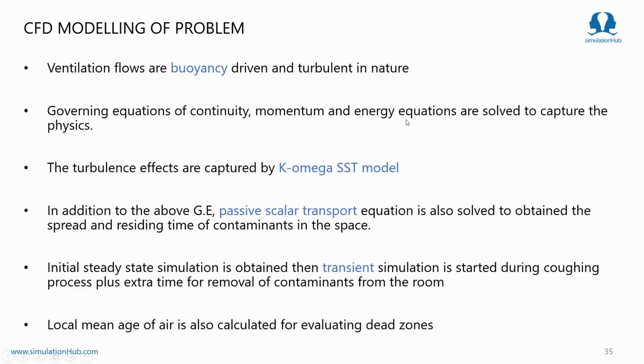Apart from that, we also need to solve another governing equation to give the contaminant spread and residence time in the space. Here, as our contaminants are airborne, like tiny microparticles that are only carried by the airflow currents, for these assumptions we have modeled this physics using the passive scalar transport equation. So in addition to the 3 governing equations, we solve this equation as well.